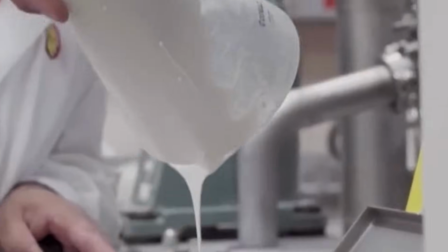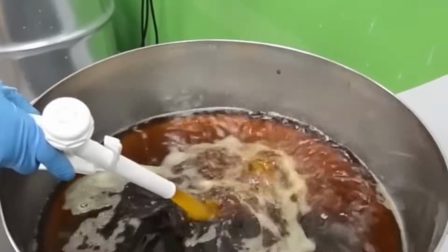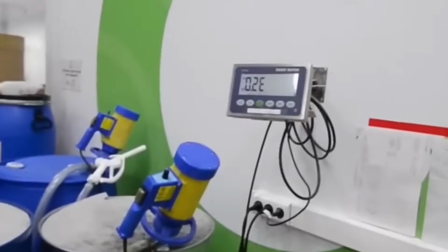Flat-folded cartons are erected using vacuum grippers and mechanical pushers, then held open under guide rails. Each tube is inserted automatically, and informational leaflets are added if required by formulation. Cartons are closed using hot melt glue applicators or tuck-in flaps depending on design.